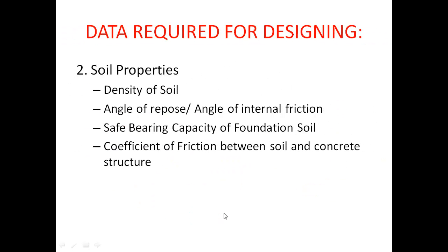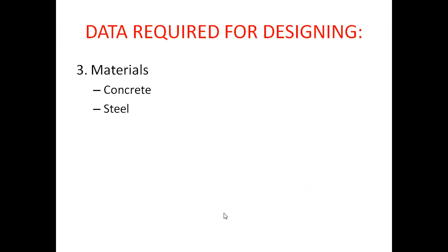Then we need the material properties, meaning what materials we are using. We need the grade of concrete: is it M20, M25 or M30? And the steel grade: is it Fe415 or Fe500? Nowadays we are not using Fe250, so I am not talking about it.